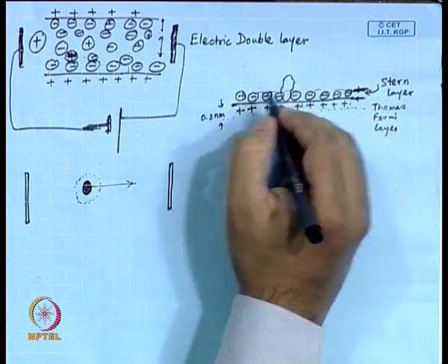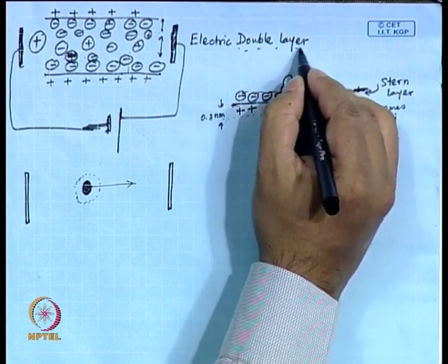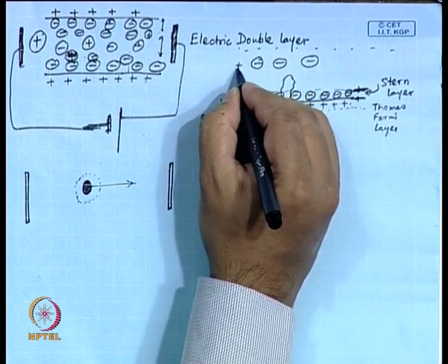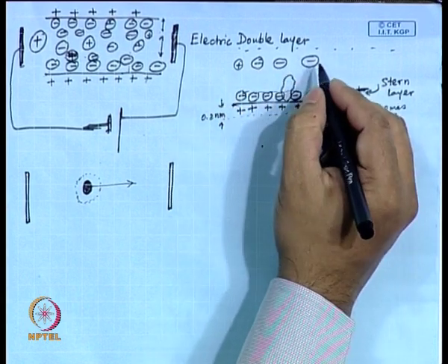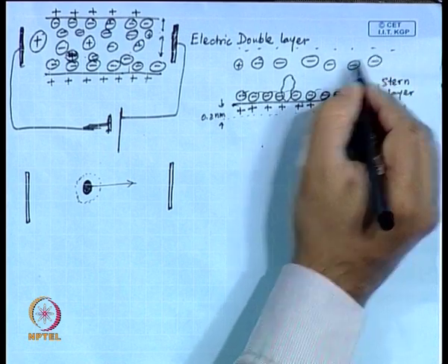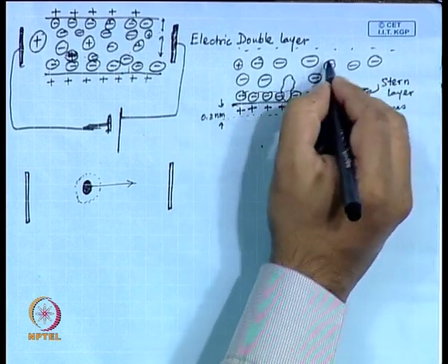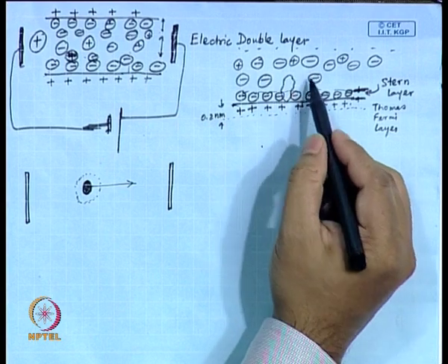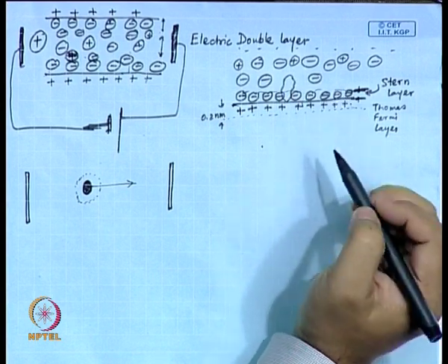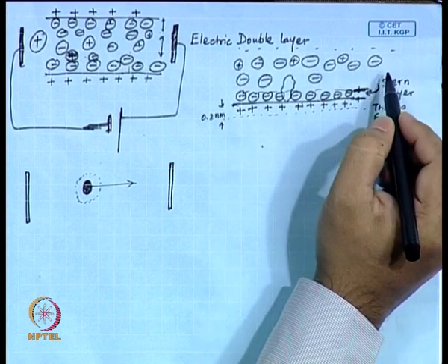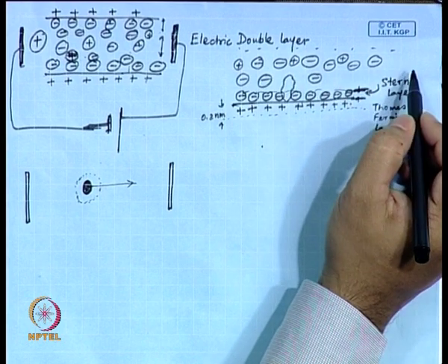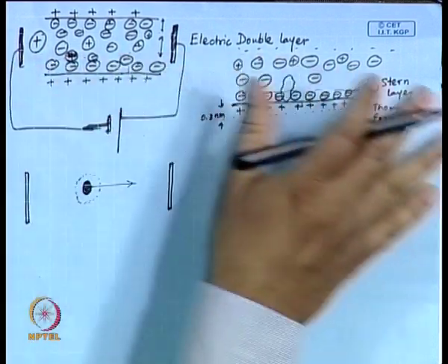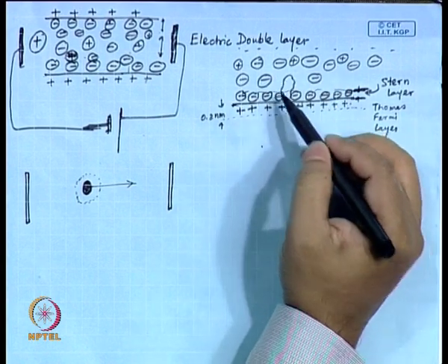what researchers have found is that there exists another layer, probably on a much wider level, where you have predominantly minus charges and some plus charges as well. Okay, but some plus charges here and there. And these charges are mobile, they are not adsorbed by the wall. These charges can be pulled by putting an electrode. These charges can give body force to the Navier-Stokes equation and pull the rest of the liquid as a whole. So, these charges are what matter.